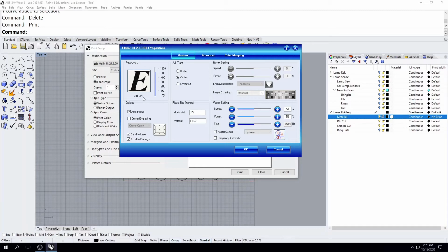So if I have a different material, like a big block of wood that I want to engrave something in, that's going to be thicker than, say, this thin cardstock that we're going to be using. So for right now, just make sure that autofocus is on. Now, our piece size, that's the material size we're going to use. Your material size can be totally different, but for now, we're just going to stick with 24 by 18, which is the max bed size.